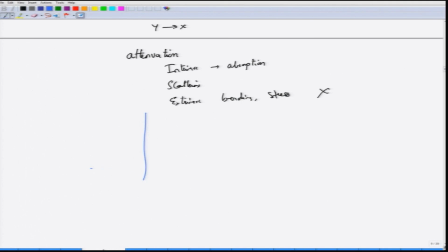But if you look at the attenuation versus wavelength curve for a silica fiber, you will see that attenuation is very large at very short wavelengths, less than 400 nanometers. Okay, and this happens because of the electronic transitions. At very small wavelengths, the energy of the photons is quite high, because energy is inversely proportional to lambda. It causes the materials in the lower state to go to the upper state, thereby inducing a transition. So, these electronic transitions cause attenuation of the signal.